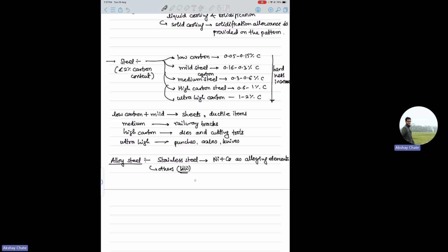But then what happens when you talk about non-ferrous materials? They have low melting points, and there are special challenges. First is, they have non-uniform chemical composition or segregation, loss by evaporation, air aspiration, and many other things. So those kind of things come into the non-ferrous category. So those things are also discussed in the class. You can just have a look.